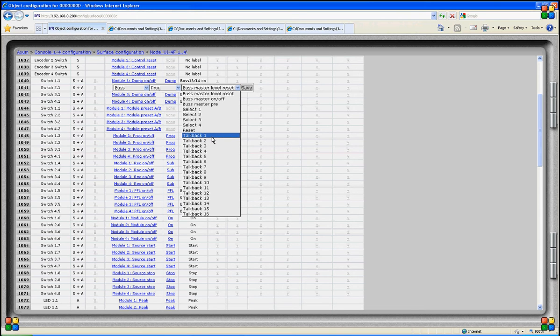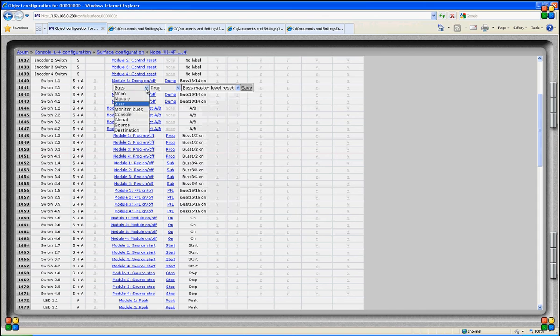When the talkback signal is generated on the bus output, the mixer will check on which output and on which destination this bus is active, and then will eject the talkback signal. So, talkback is not really routed to a bus, but software will check which buses are routed to which destinations, and there a talkback signal will be generated.